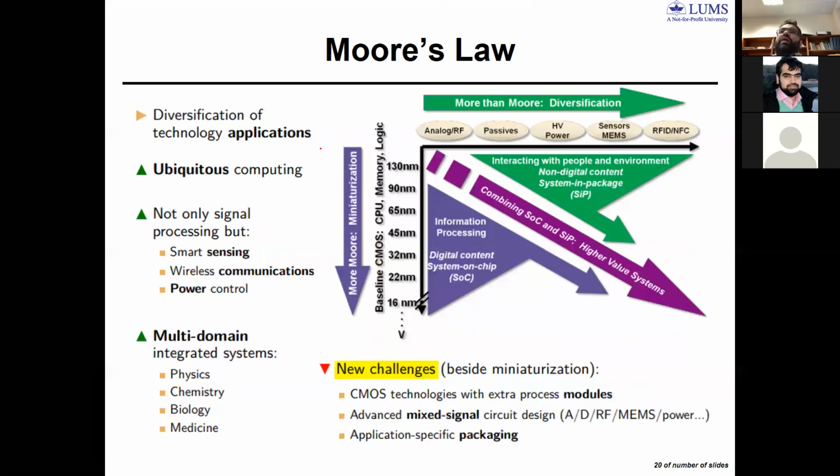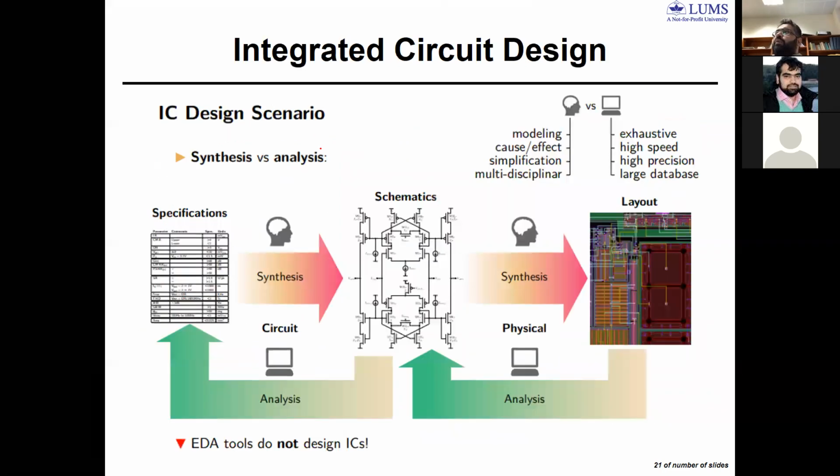And this is like the nanometer-wise, which I mentioned. Okay, for analog and RF, we want good, we remain in 130, 65 nanometer. In digital, we definitely want to go for a lower end. We want to go for 5 nanometer, 10 nanometer. What is the advanced coming? But when we talk about mixed signal, where both analog and digital are present, it's okay to be in 180 to 65 nanometer to get the maximum benefit from those things. So that's a little bit about Moore's law.